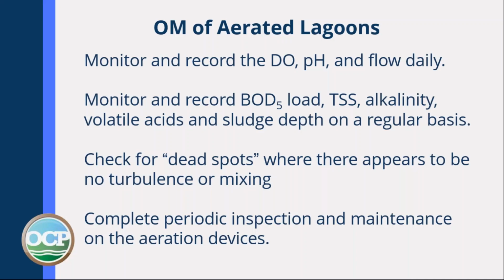Monitor and record BOD load, TSS, alkalinity, volatile acids, and sludge depth on a regular basis. Check for dead spots where there appears to be no turbulence or mixing. If you're using an aeration system with aeration heads at the bottom of the lagoon, one may have become plugged. Complete periodic inspection and maintenance on the aeration devices should be done regularly.